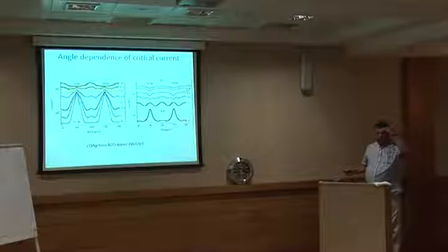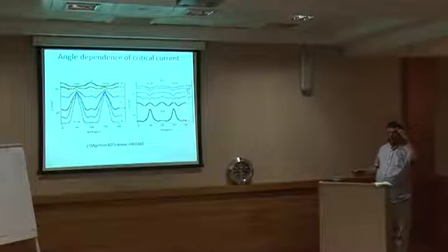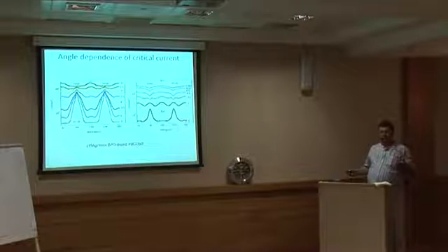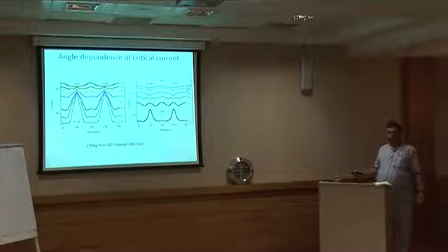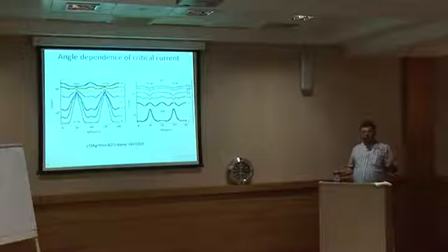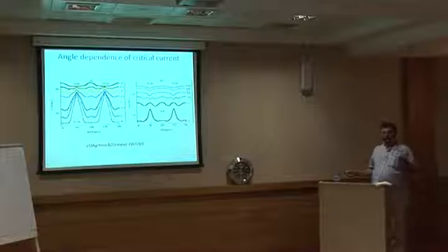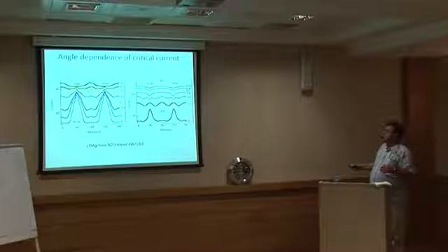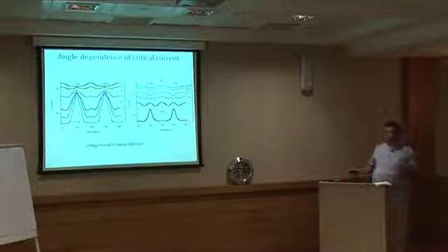As we discussed yesterday during your question time, depending on the equipment you are doing, the type of solenoid, you would like to be sure that parts of your solenoid which are subjected to applied field at different orientation will not surpass critical current in that direction. So if we are sure that regardless of the angle, critical current is almost constant, which is this case, this is what we need.